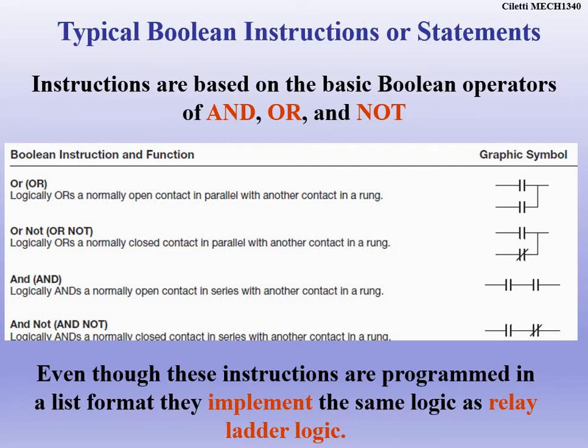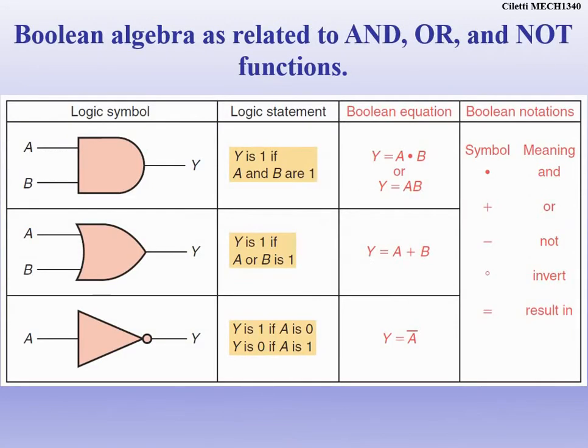If you remember that a NOT gate means it's a contactor with a line through it, means normally closed contactor, that'll help you understand the NOT gate. And so just remember, ANDs are in series, ORs are in parallel, and then NOT gates have the line through them. Very simple for us to take a logic expression and turn it into ladder logic and write it.